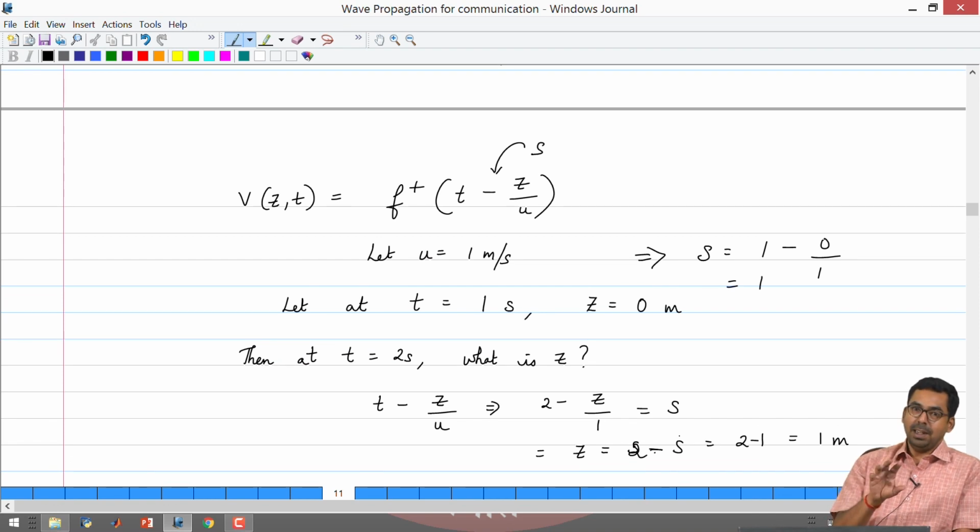So, the conditions that dictate whether the voltage wave is going to travel forward only or it is going to travel backward, and if the backward voltage is going to have the same sign as the forward voltage or inverted sign, are all governed by what are known as boundary conditions, and we need to understand these boundary conditions very well.